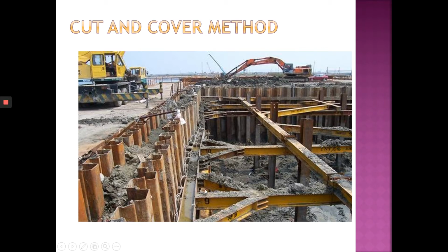Then they will have strutting. Okay, semi-strutting, and they will have braces, bracings around. Okay, so around the perimeter, they will use sheet pile. So this type of retaining wall is also normally temporary. It's not permanent. They will pull it back.